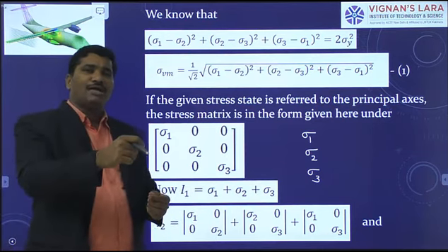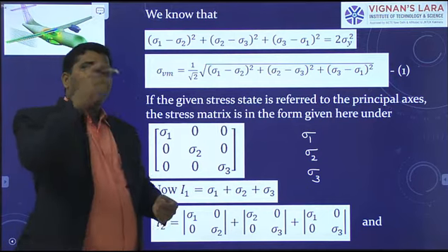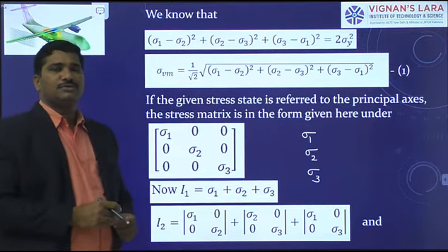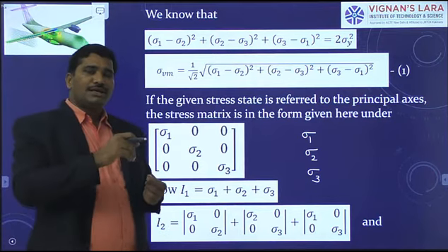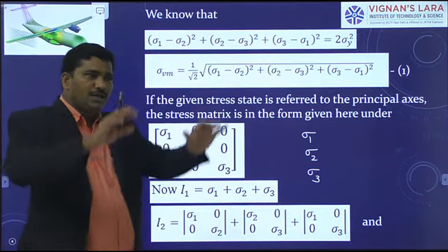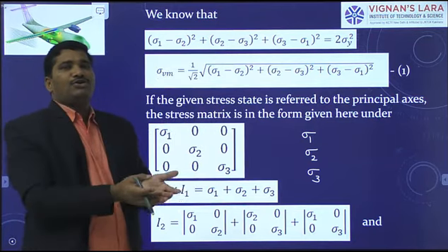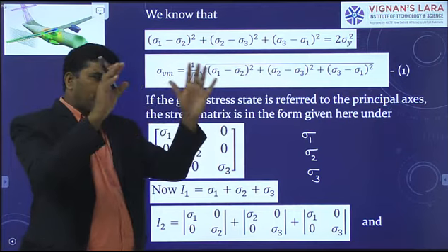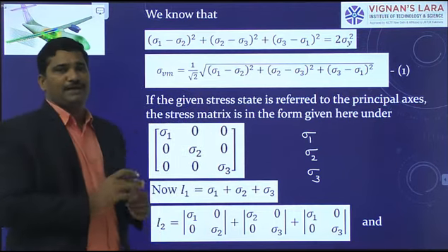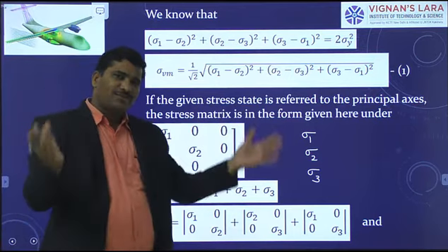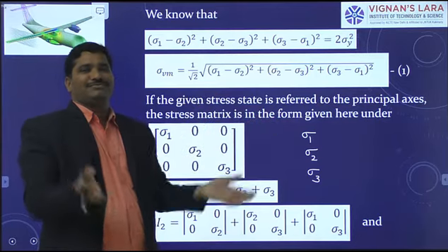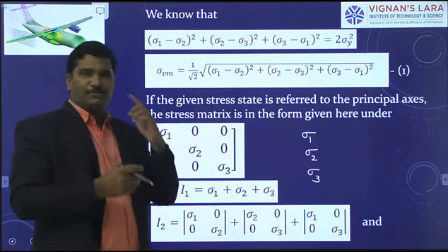At every point, the pressure acting on the surface of this body is normal to the surface at the same point. Moreover, the intensity of the hydrostatic pressure at every point on the surface of the body is also the same according to Pascal's law. This case we can consider as a body under three-dimensional loading. Therefore, it is a three-dimensional problem.